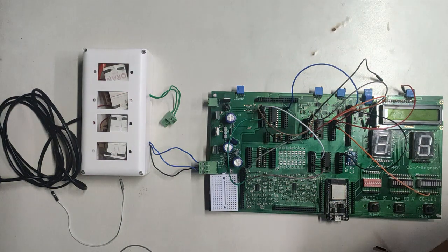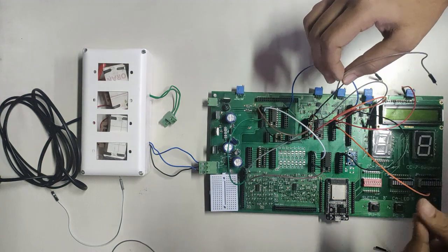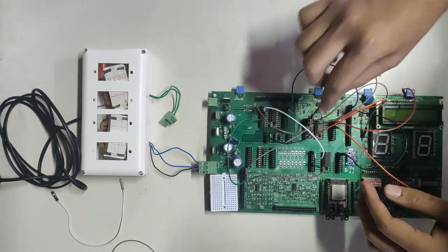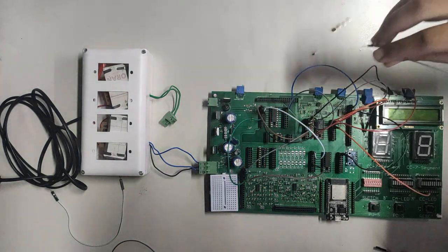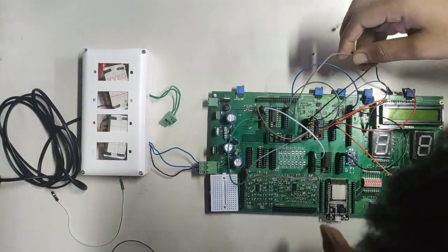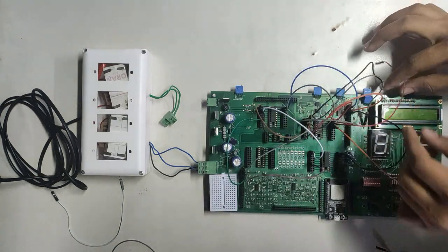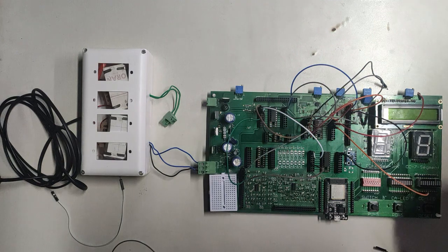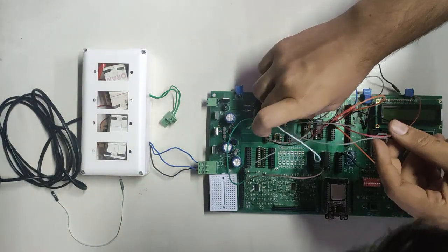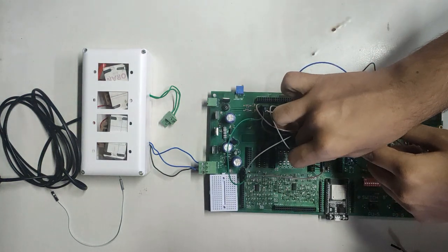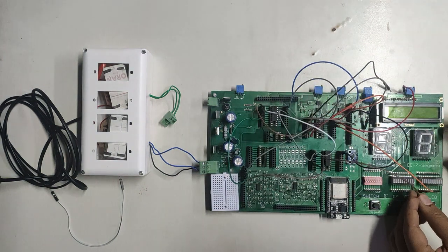Now there is the second AND gate, whose input is the output of the first XOR gate, which is the sum, and the second input is nothing but the C. And the output of that AND gate is given to the OR gate as the input, and both the inputs add and give us carry. So that was the implementation.